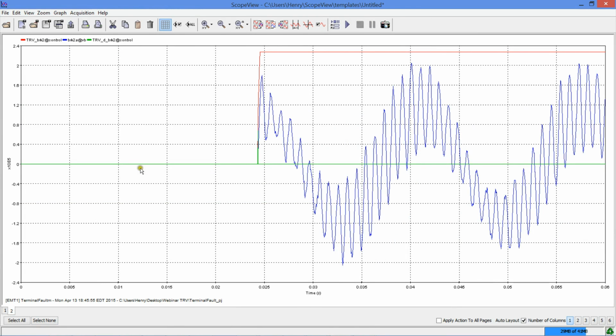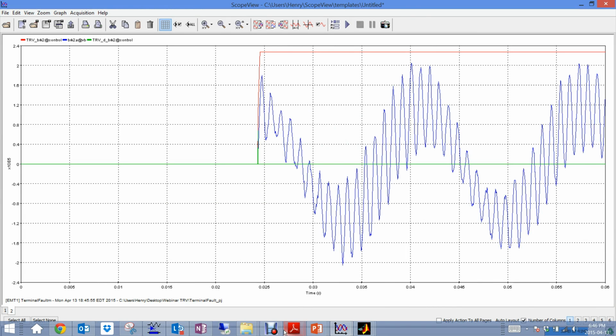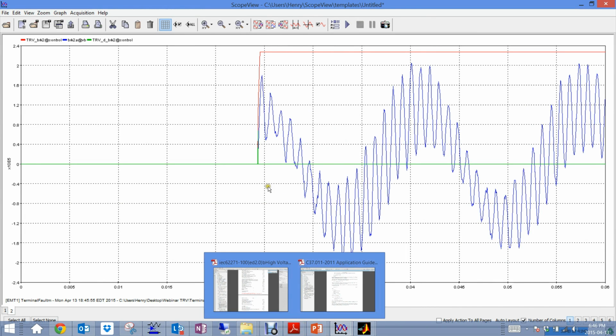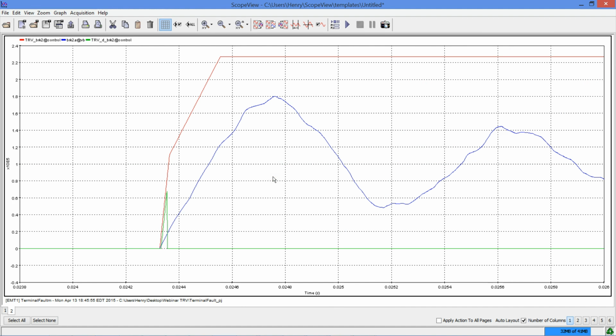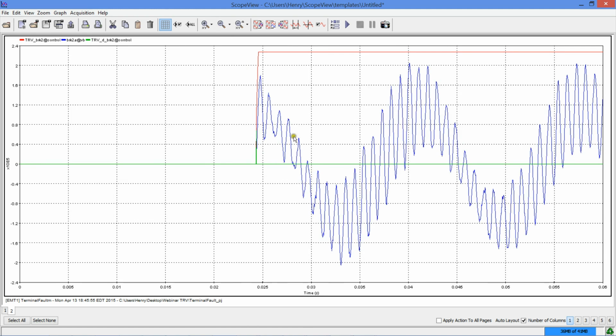Okay, it's better now. So see, as soon as the breaker opens, we have here the envelope that the breaker has, according to the standard, which has a short circuit current interruption capability of 30,000 amp. Here is the envelope. Right, so if I zoom on it, remember in that test we're interested in the worst overvoltage. We have a pretty good margin here, so it's fine for this side.